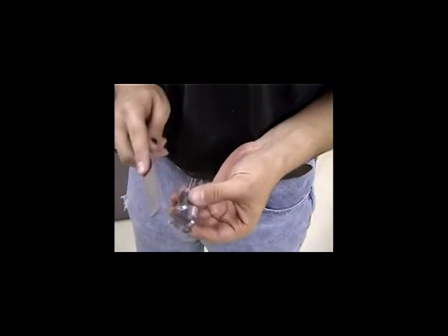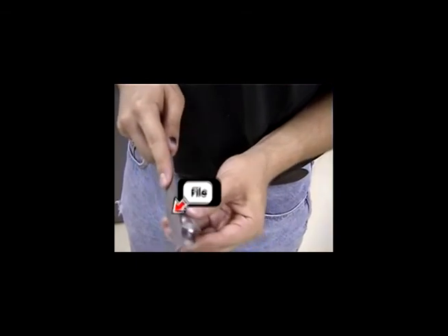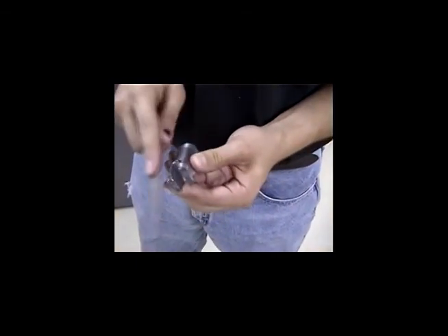The milled part often needs to be filed to remove any metal burrs or rough edges. Use care and patience when filing to avoid cutting or abrading yourself.